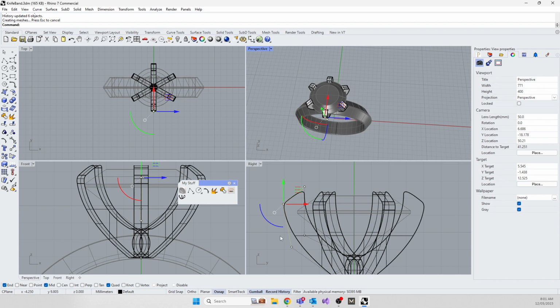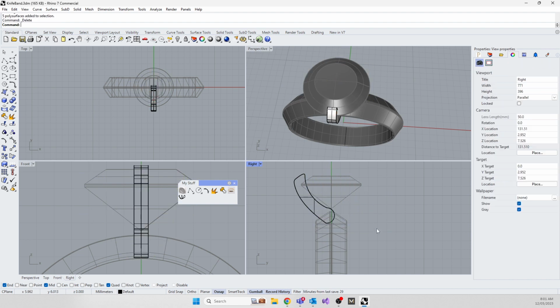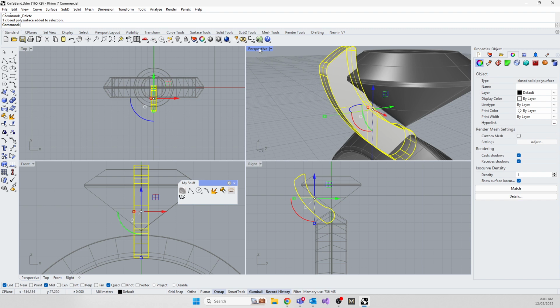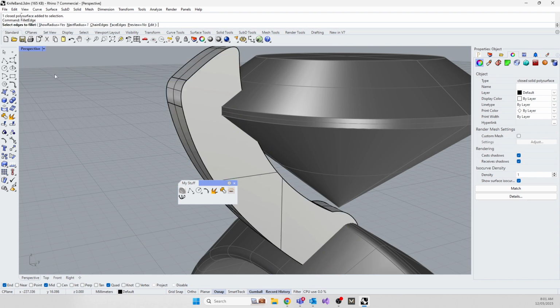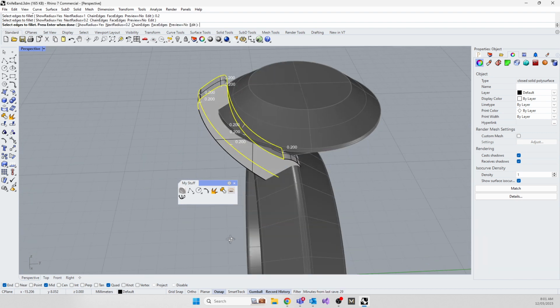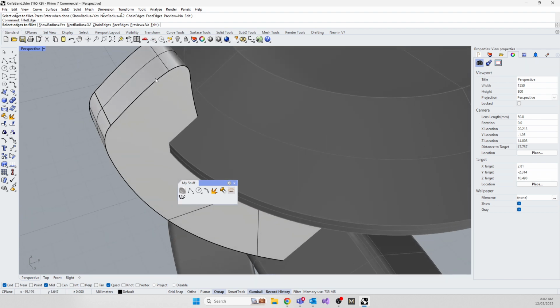When you're ready to go to production with this, it looks crap. So what you would do is just delete these guys, because we now know that we're good. And you come on this guy and you do a fillet, make everything look nice. So you do a fillet edge. I think about 0.2 is going to be fine. I'm going to grab all these edges and hopefully it doesn't break. I'm not going to grab all those edges apparently, so I'm going to grab that. Let's grab you and you and you and you.